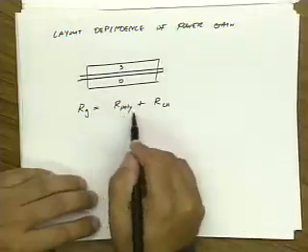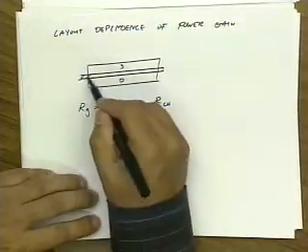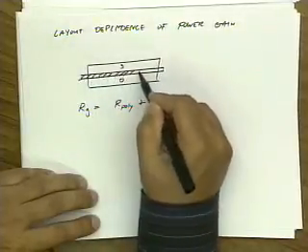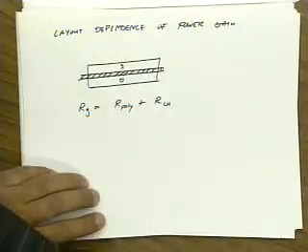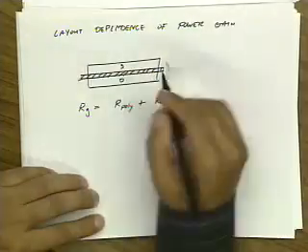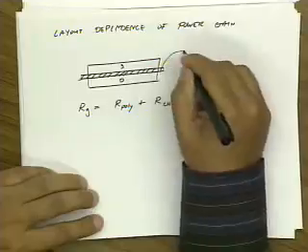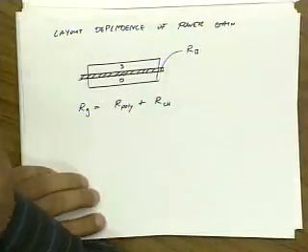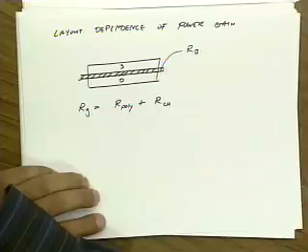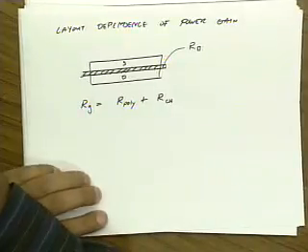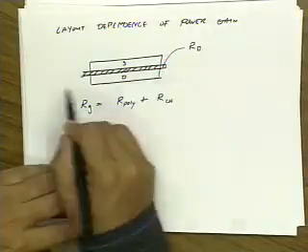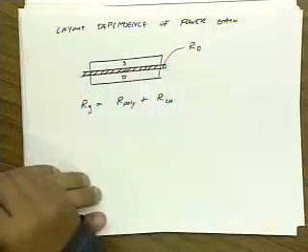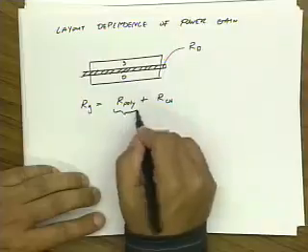Now the poly resistance is quite easy to understand. It's proportional to the resistance of this gate finger, right? So usually when you design a transistor, someone will tell you, yeah, this poly is silicided and it has such and such sheet resistance, right? And of course you want to get the one that has the lowest sheet resistance. So you just calculate the physical resistance of this, and that contributes to this term.